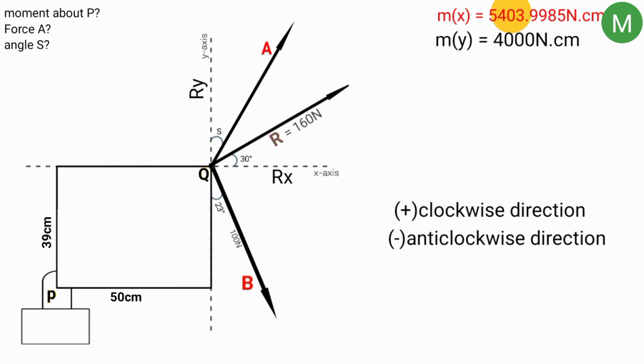taking moment of x now, the force here is the same as the force acting here, on the same line of force. And if the force is acting here, it is definitely going to rotate the board to this direction here, which is the clockwise direction. And therefore, the moment caused by the x component is positive.